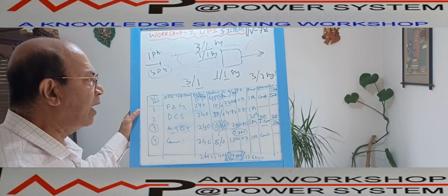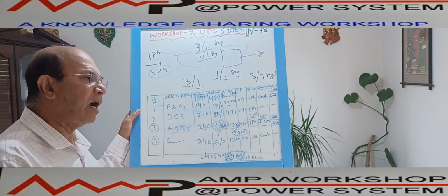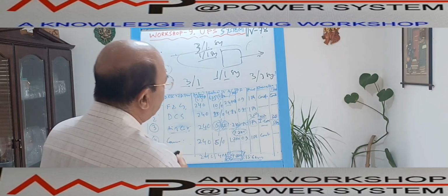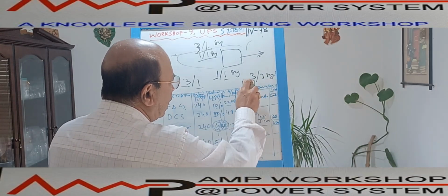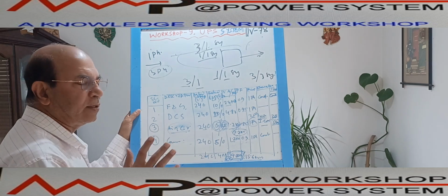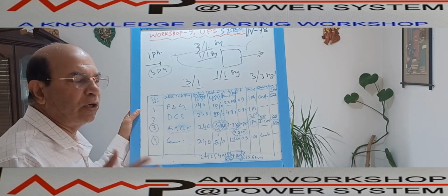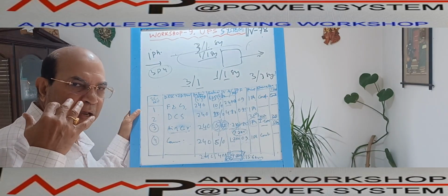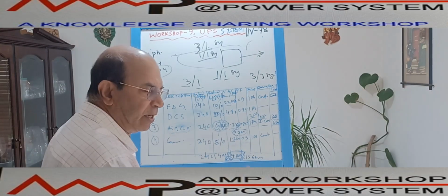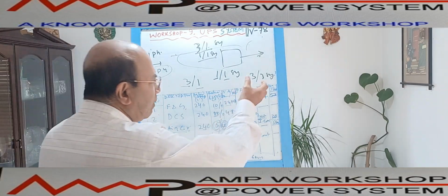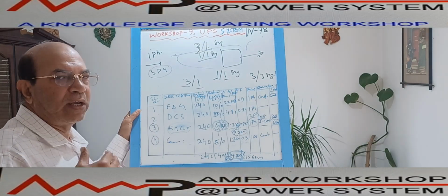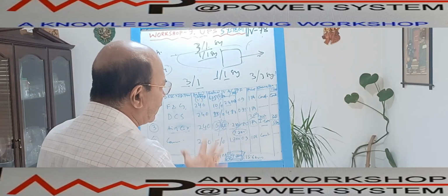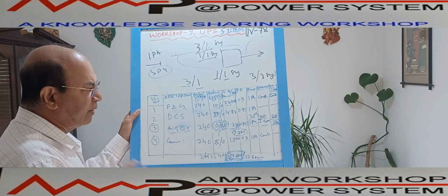And third option, if any of the load is three phase, then I don't have any other option without going output three phase. So input obviously will be three phase. So 3/3 system will be in two cases. One case is if any of the UPS load is three phase, we have to go 3/3 system. And if the total kVA requirement for the UPS is more than 7 kVA, then it will go by 3/3 system. Otherwise, we can go 3/1 or 3/3 system. These are the normal practice for the UPS system deciding.